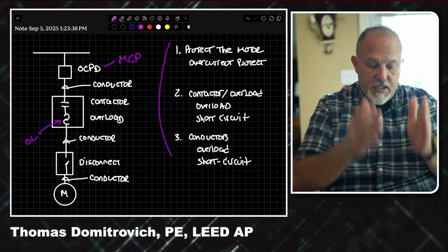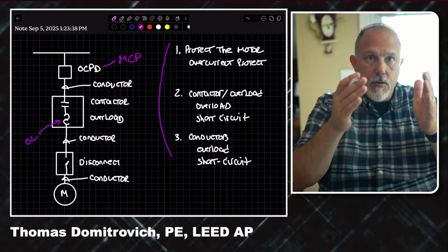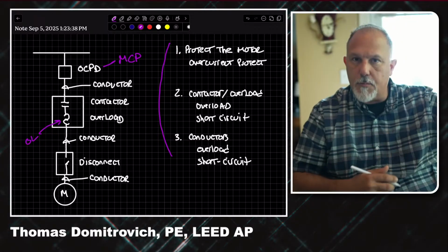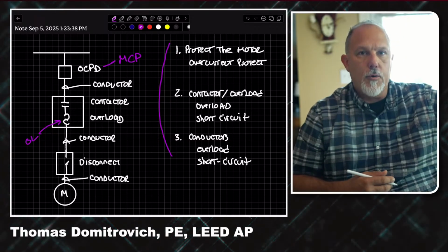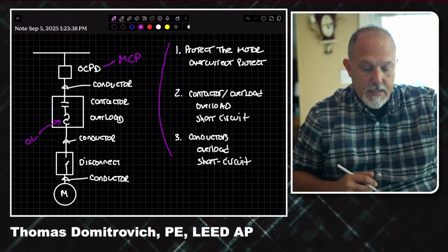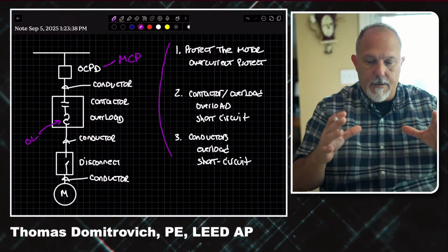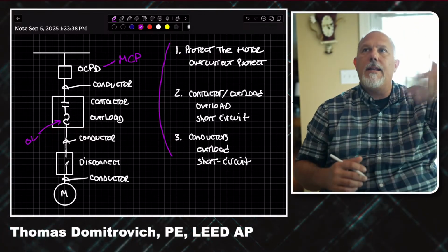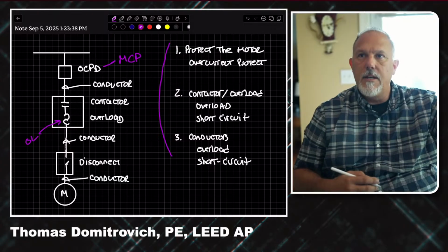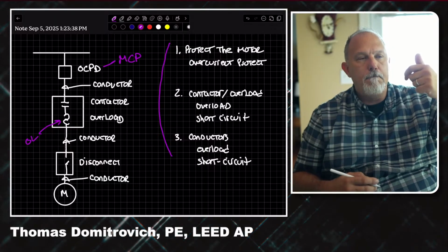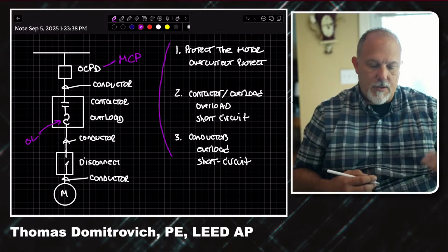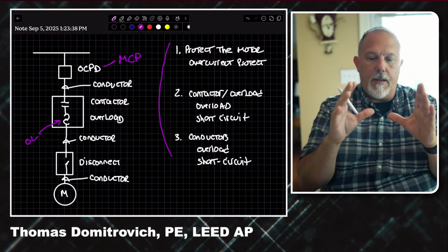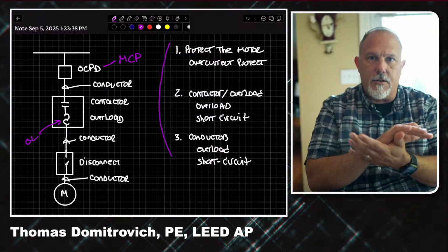But this, I think, is your standard basic motor circuit. You've got your overcurrent device, you've got a conductor coming off of the circuit breaker, whether it be a motor circuit protector or a circuit breaker, and we'll go through that process. Then you're going to feed, and what I've seen is, I've seen I think Allen Bradley, Cutler Hammer, Westinghouse, Eaton, Schneider, etc. I remember purchasing and installing a motor starter. Basically, it was a contactor and the overloads.